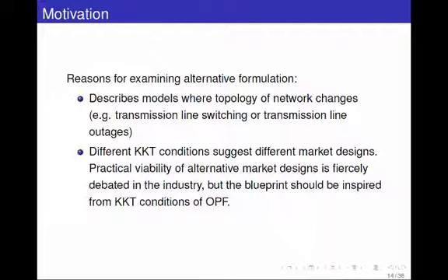If you remember last week, we saw one model of the power flow equations with the PTDFs, where we were basically mapping production at buses to flows on lines using PTDFs, these FKNs. The alternative version we saw was mapping production at buses to bus angles at buses. Same exact thing in terms of physics. And here we were using these reactances.